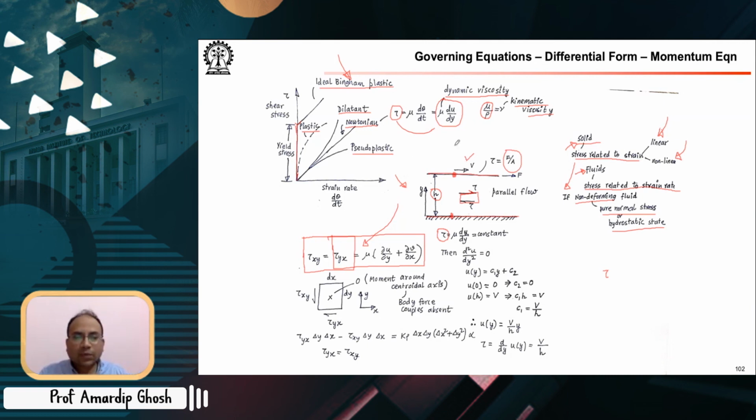We don't know exactly what kind of velocity gradient, but at least we can say that since the cross-sectional profiles look similar once things have settled, there is no acceleration as you move along the x direction. So then there is no net force on this blob of fluid.